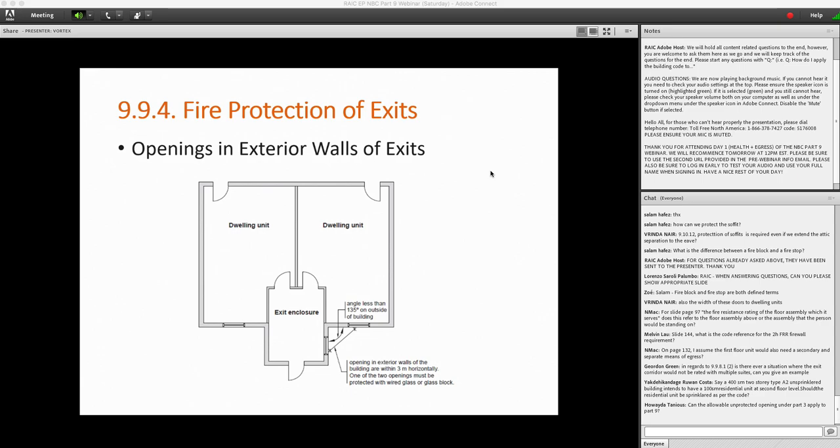Question 9 is 9.9.7.12. So 9.9.7.12 states, roof intended for occupant load more than 60 people need to have at least 2 separate means of egress. Where in the NBC does it state 60 people or more related to table 9.9.7.4 for suites?